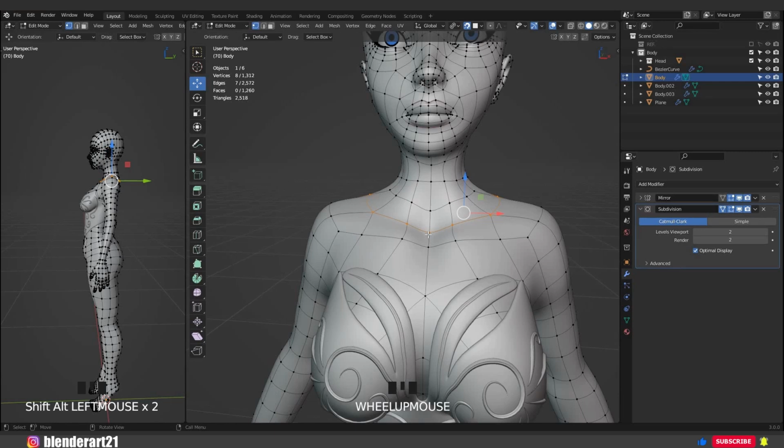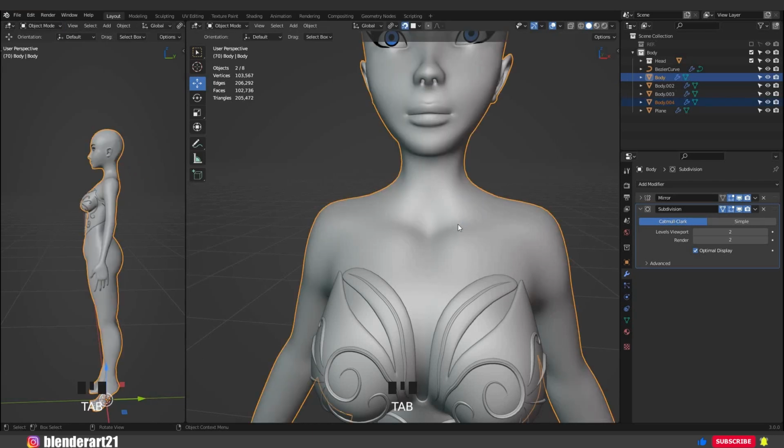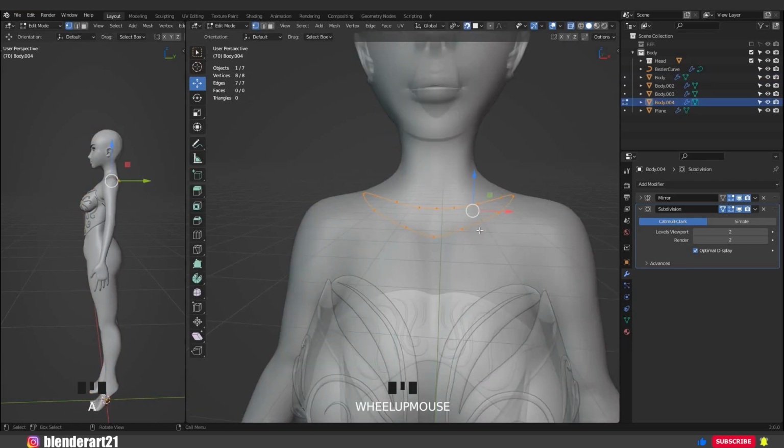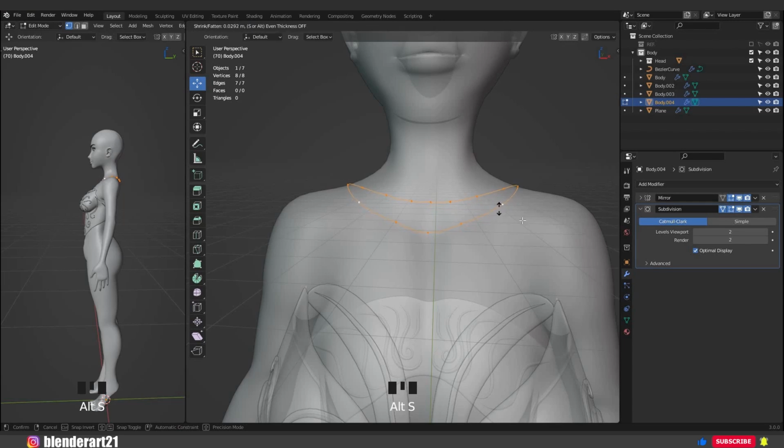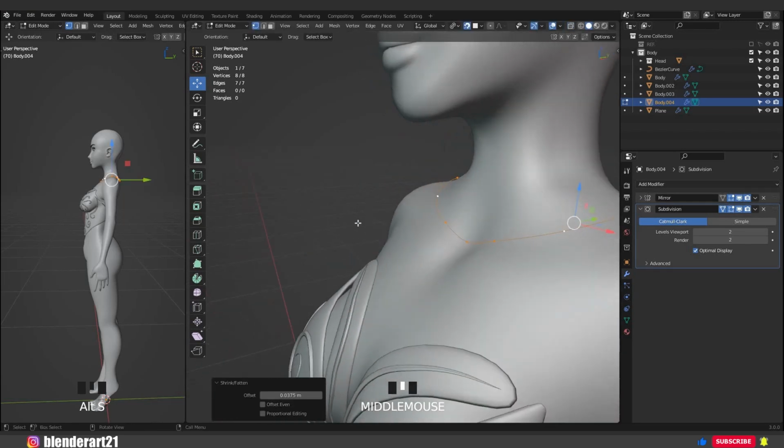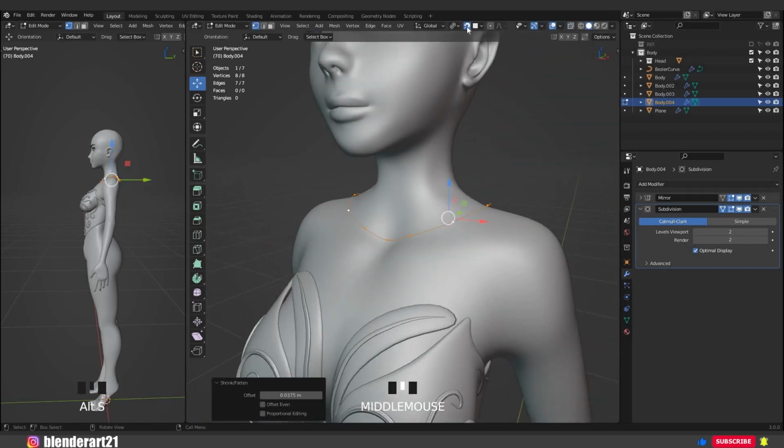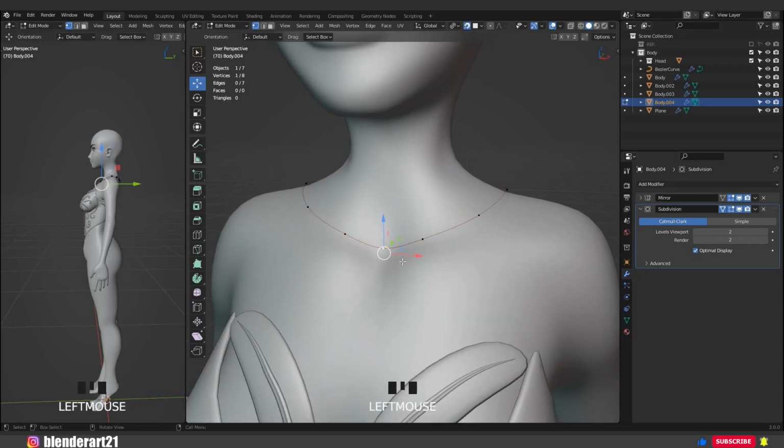So in the vertex select this loop, Shift D to duplicate, mouse right click, P, enter to separate the object. Select the new object, A to select everything, S to scale it a bit. Now we can use the snap tool. To activate snapping into the face, click on this icon, make sure to turn on the magnet icon into blue. Now we are ready to go.